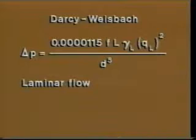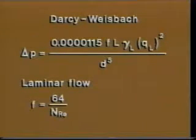In the case of laminar flow, the friction factor F is calculated using the Reynolds number, where F equals a constant divided by the Reynolds number. Turbulent flow calculations are based on an empirical pipe roughness factor and the Moody diagram. Techniques are explained in your manual. These equations are valid for single-phase liquid flow, a condition that seldom exists for produced fluids. Nevertheless, these equations may be applicable, and they certainly are useful when applied to such conditions as those present in water injection facilities.